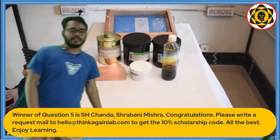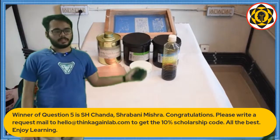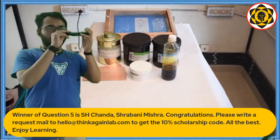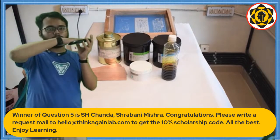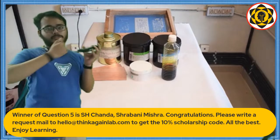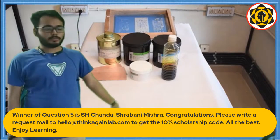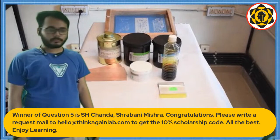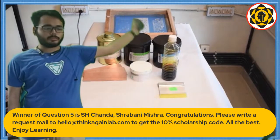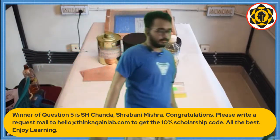And next is finally this copper clad board. This is what I was talking about earlier when I said about the printing and stuff like that. So these are the boards. This basically is a plate of fiberglass. It's coated with copper plating, a thin copper plating, so thin that you can scratch it with a screwdriver. So don't scratch it. So yeah, that is the copper clad board. And finally, this PG. This is basically used for that screen printing. It's the stuff that you pull. You put the screen on the copper board.